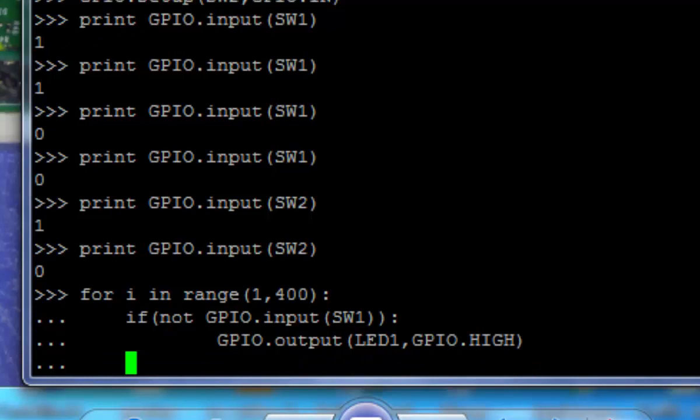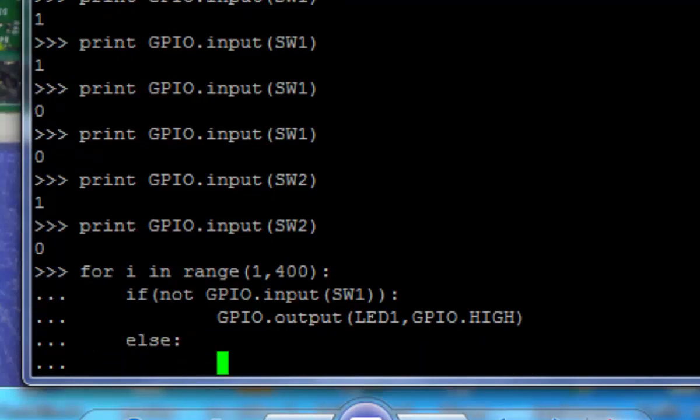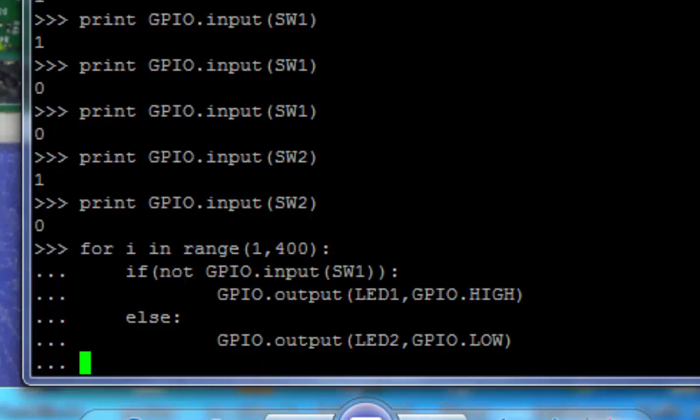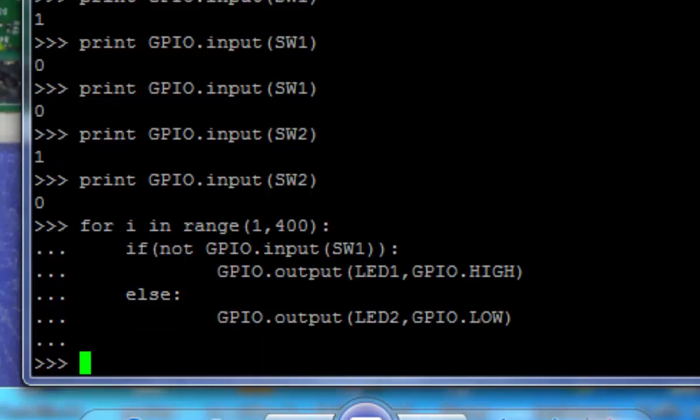The next thing is in the else form, and what to do is just turn off the LED. So this will turn the LED off. When we press the switch the LED will be on, and when we release the switch the LED will be off. That will be the simple logic for this. And when we press the button, the LED will be on and it will be off, because these statements are executed so many times. The duration for executing this process will be very fast.